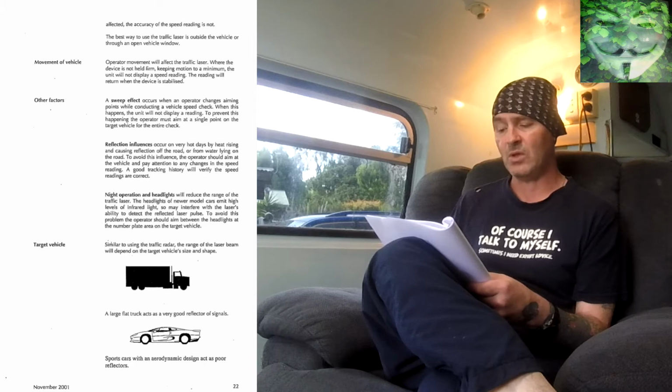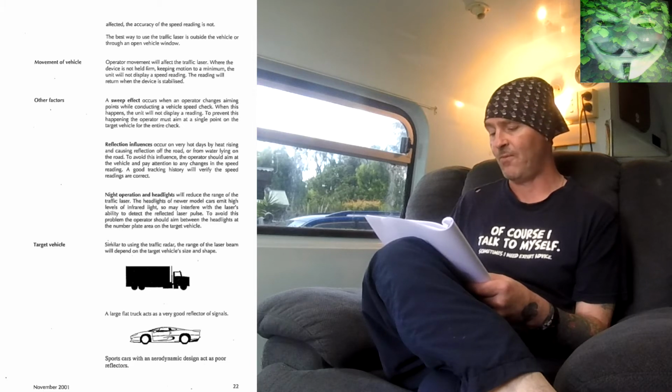Reflection influences occur on very hot days by heat rising and causing reflection off the road or from water lying on the road. To avoid this influence, the operator should aim at the vehicle and pay attention to any changes in the speed reading. A good tracking history will verify the speed readings are correct.